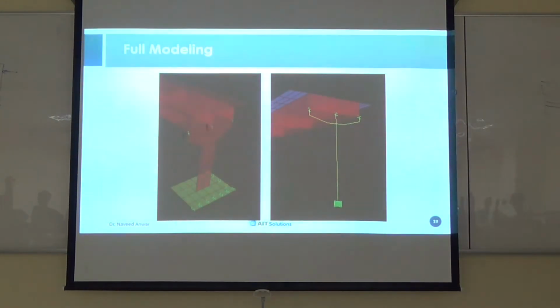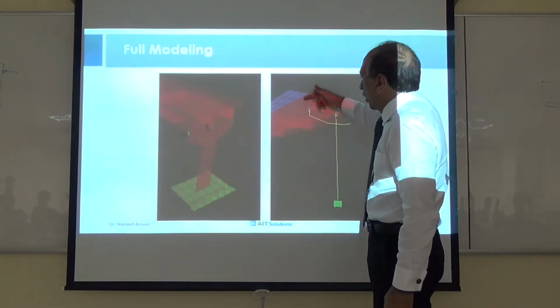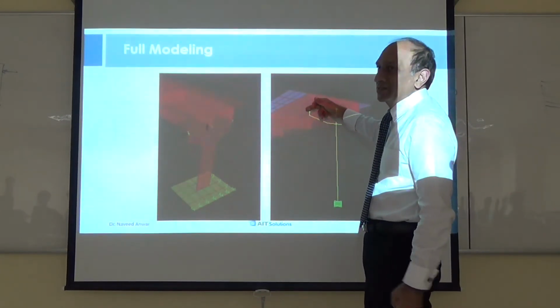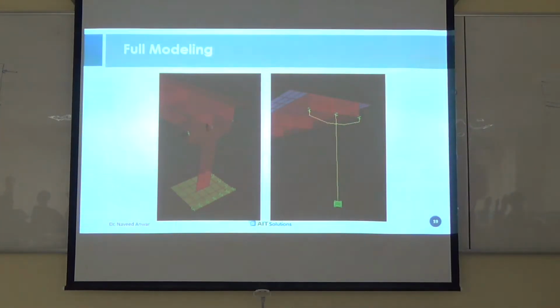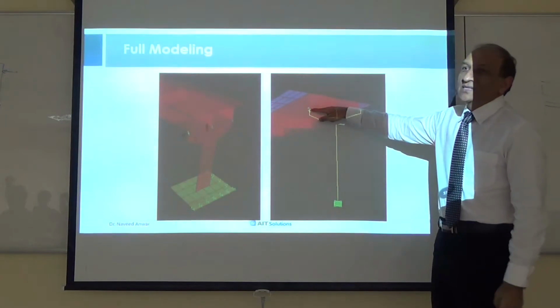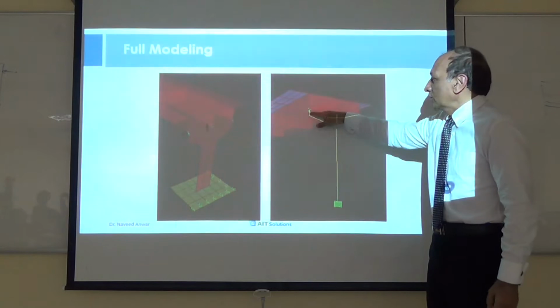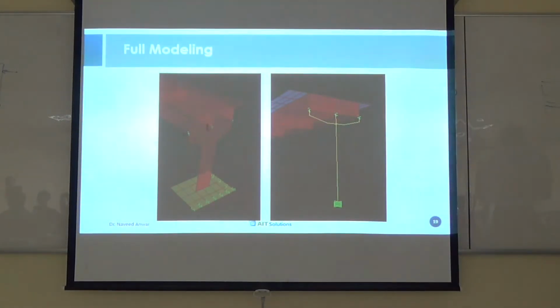But now we can model it realistically using either shell element or offsets, physical or use the constraints. So we can do many things. There are many tools you can use to take care of this offset. But the point is that this modeling of the deck, how to model it correctly, what elements to use, is a lot of work to understand completely, but it matters on the efficiency of the final design and the prediction of the correct behavior.